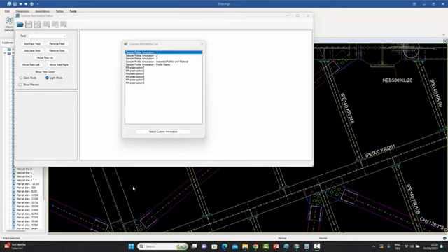Now, you might be wondering why only two custom annotations appeared under the profiles annotations, whereas I had shown you a lot in the custom annotation editor. So I've put it back on so you can see them again. There's 1, 2, 3, 4, 5, 6, 7, 8, 9, 10, 11 custom annotations. The reason why only two of them showed up over there was because only two of them had the category of profile, this one and this one. The first three were for rebars, and the last six are all for plates. And we can see these KM plate option 1, plate option 2, 6 different types of annotations for plates.